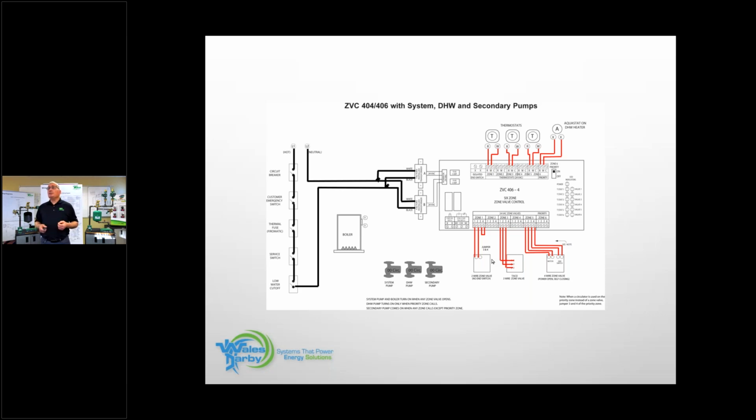The zone valve where you see 3 wires, that would be my Taco 571. When we do our wiring class, we show you that valve. It is a 3-terminal, but it actually is a 4-wire. But when you use it with our ZVC panel, it's just terminal 1 to 1, 2 to 2, 3 to 3, and that zone valve is done. Anybody's 4-wire zone valve, if we're going to go with the standard everybody's comfortable with, the Honeywell, your 2 yellows are your motor. That's going to go into terminals 1 and 2. Your 2 reds are your end switch. They're going to go into 3 and 4.